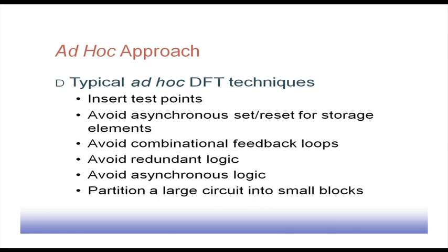However, this redundant logic removal is not always advisable, because designers, to avoid hazards and glitches, may like to put some extra gates in the circuit which are actually redundant, but that helps avoid them. So though test engineers will ask for that, the design engineers may be telling the other way.